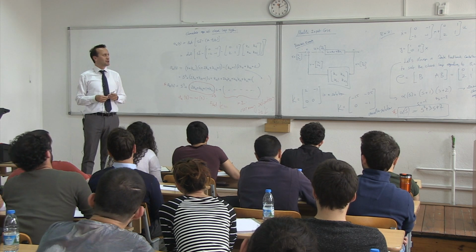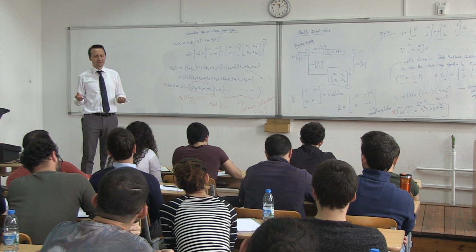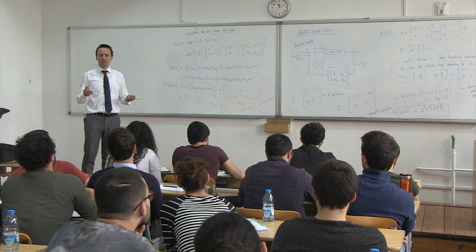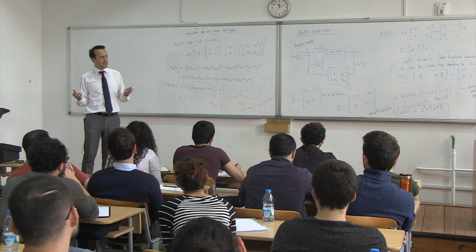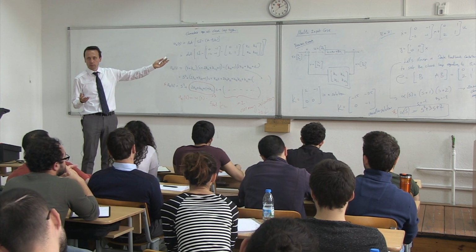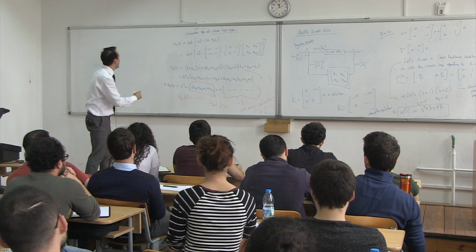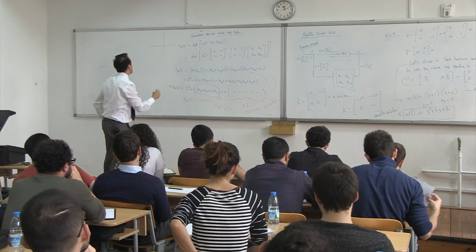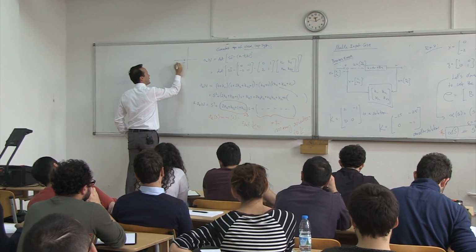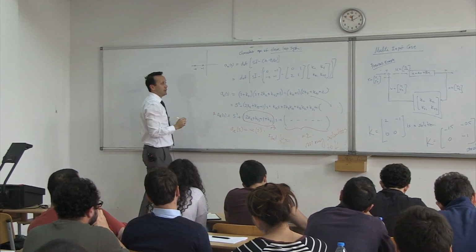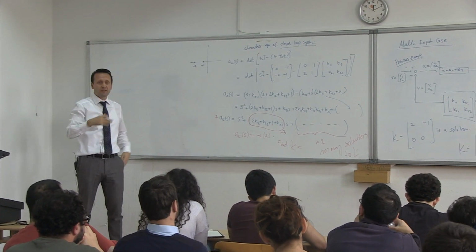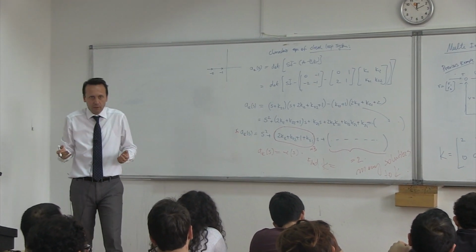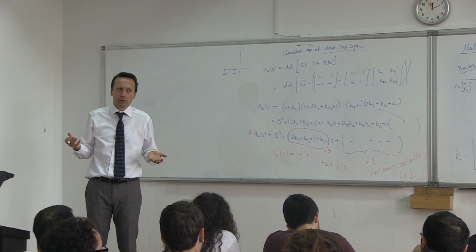So. Question is, of course, which one should I choose, right? I mean, which one is better than the other one? I mean, they all satisfy the closed loop solution. The closed loop solution was supposed to be at -1 and -2. So the closed loop has now roots at -2 and -1, and all of these K values, they satisfy this, so it's good. Question is, which one should I really choose?